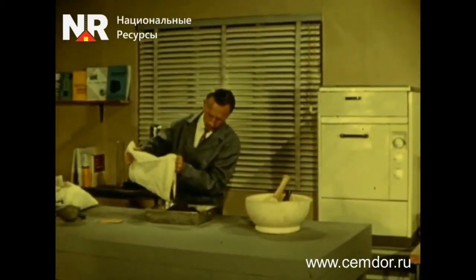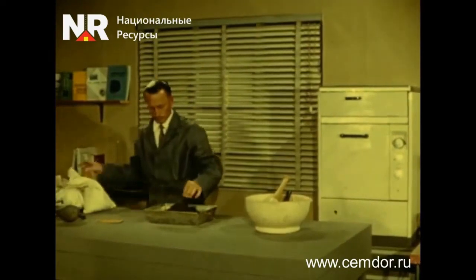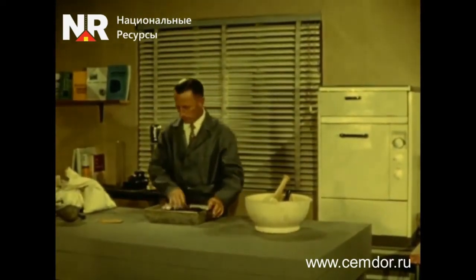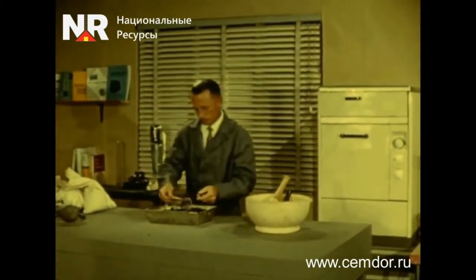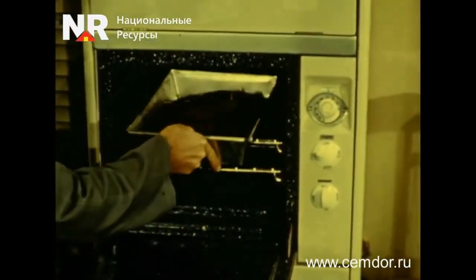When selecting the soil concrete mix, the first step is to determine the maximum soil density at its optimal moisture content using the standard compaction method. For this, the soil sample prepared for testing is dried in a drying oven to an air-dry state.